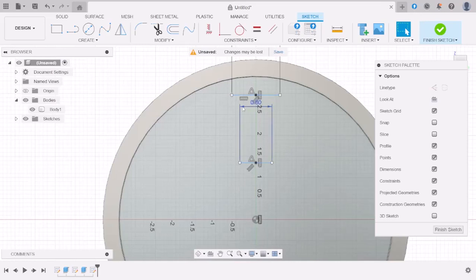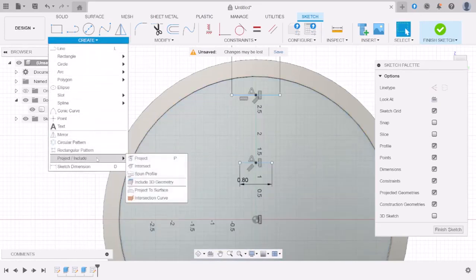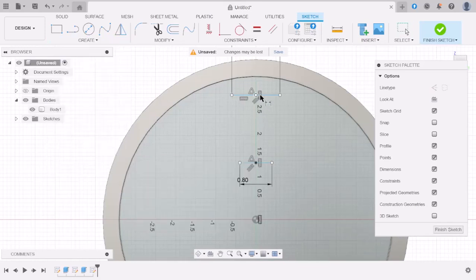If you want to constrain them fully, what we can do is, let's move this way over here. We can give a dimension. So come to sketch dimension, click on this, click on the first line we want to dimension, and click on the second line we want to dimension too. And let's say we want a total length of, I did not measure, let's say 2. Let's say more or less a 1.8 or 1.7.